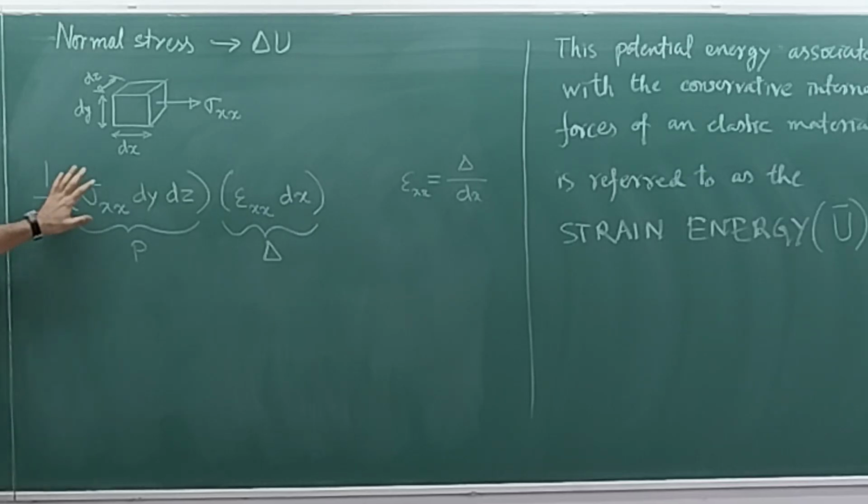Okay, so this half is very important. This half, please note, arises fundamentally because of this linear relationship. We are proceeding from zero deformation to that final deformation delta, as well as this linear relationship. That is why that half is appearing. Had it not been the linear relationship, it would not have appeared. Only because this x is there, that is why that x square by 2 is coming.